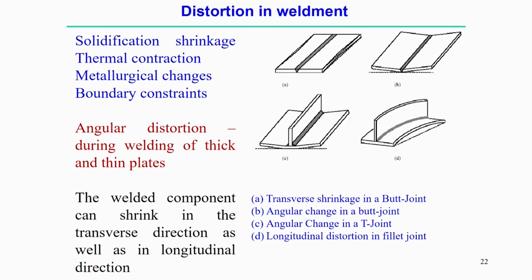So, whether the distortion happens in a concave or convex type, or is simply angular distortion, all can be measured straightforwardly using a simple coordinate measuring machine or some laser scanning system, with respect to some reference point.